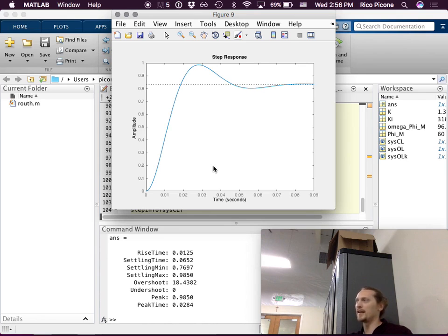You could just add in an integrator, and you would improve the steady state situation. You can just do that ad hoc if you want to, or you could design it based on a lag. And there's a lag design example in Nise if you wanted to look at how they do that. Essentially, it all comes down to shaping the Bode plot.